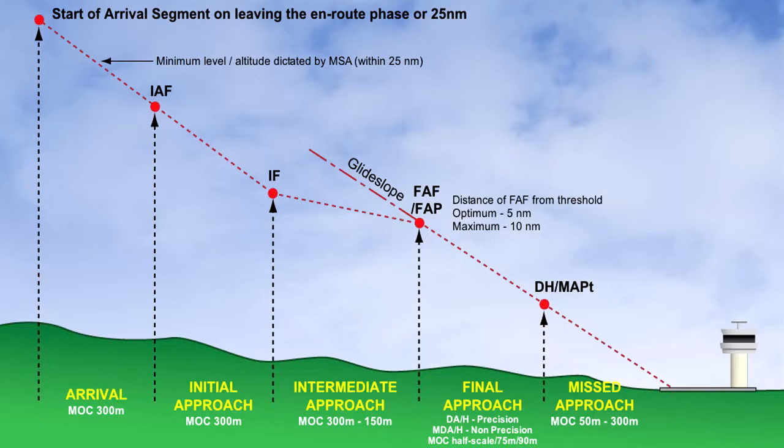Research has shown the non-precision approaches carry an increased risk of controlled flight into terrain, CFIT. The CDFA allows constant supervision of speed, power, configuration, descent path and height, an ideal situation for managing the final stages of approach of an airliner and thereby avoiding CFIT.